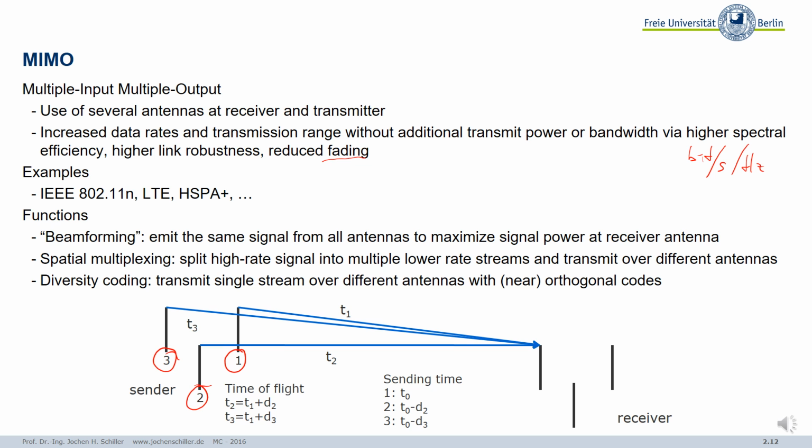And this is called beam forming. So actually, with these antennas, you're using the devices, you can follow another device. You can follow a certain user. This means you can form your beam to a certain point. And this now allows for spatial multiplexing. If you think of a marketplace with 100 users, you can form 100 beams in an electronic way, and you can directly follow those users. And the big advantage is, if you form the beams, you minimize interference with respect to the other beams. You can directly follow something.